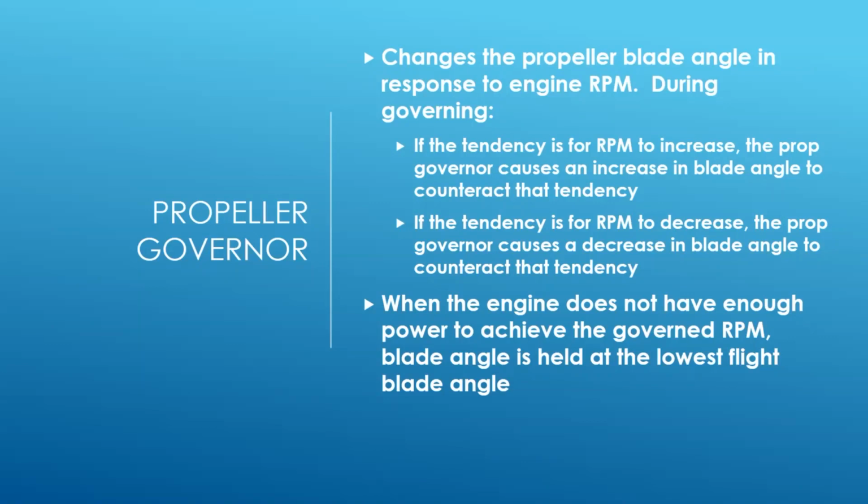There are going to be factors that can cause the propeller speed to change. What would cause the propeller to speed up? If we don't touch any of the levers, what can cause that propeller to speed up? A gust of wind, from the front of the aircraft. The propeller is trying to move air back, so if there's already a gust of wind, it's going to make it easier. That's going to allow it to spin faster at a given power setting.